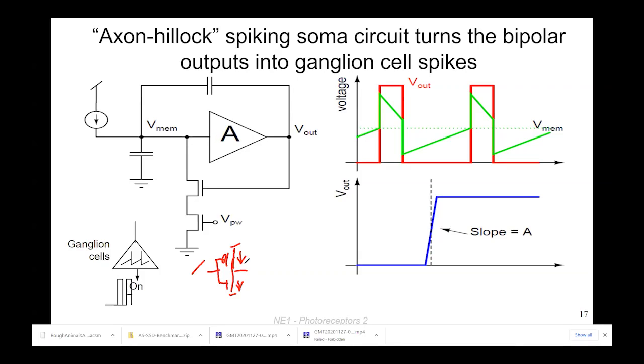And so instead, to reduce the power consumption, you use something like a static inverter. You just put a static bias on one branch, and then basically it's just an amplifier. And then the output is just like this. Now the power consumption is limited by the bias current that you put in the top transistor. You put a couple of those in series, and then you can limit the power consumption. Of course, it also limits the slew rate, but then you can bound the power consumption.